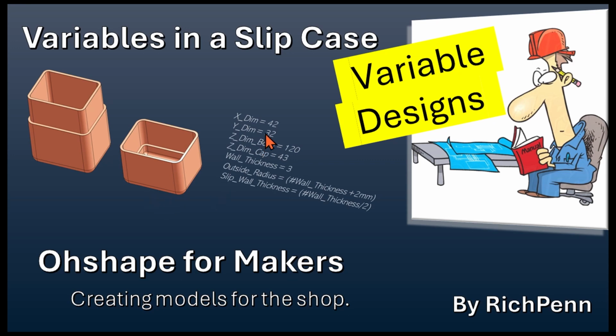We'll use a variable for the X dimension, a variable for the Y dimension, a variable for the Z dimension, a different Z variable for this dimension, and then we will have a dimension for the overlap. When we put the two together, we will dimension the wall thickness, and we will calculate, using some of the variables, the radius, so we don't get a zero corner if the wall gets too thick. We're going to just work along and talk about several things and the order to do things in and why we're doing them in that order as we go.